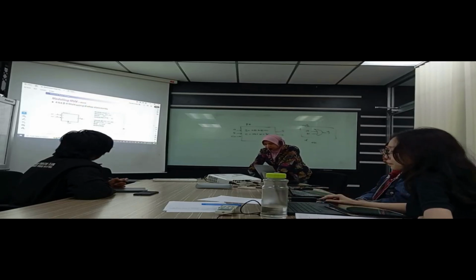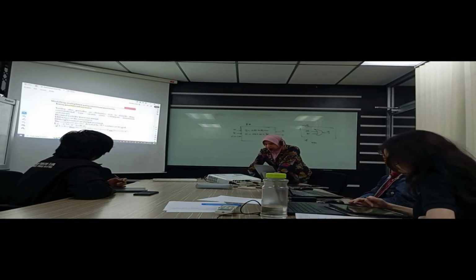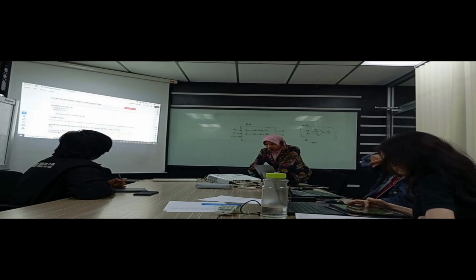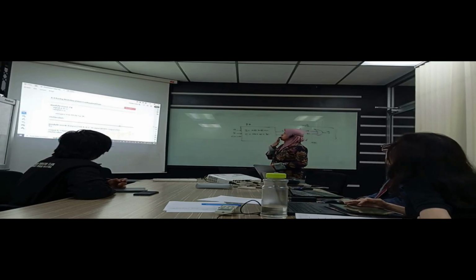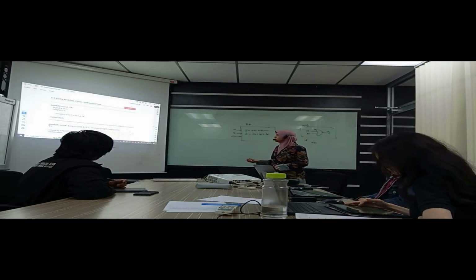Alright, so we have a few ways there. And you also can use the conditional operator for the multiplexer, like this 2 to 1 multiplexer. You can use the assign and then the Z equal to, then test it, S equal to 0.